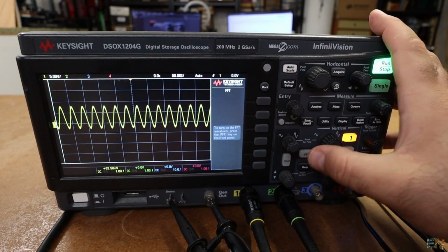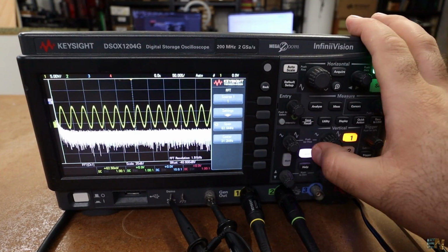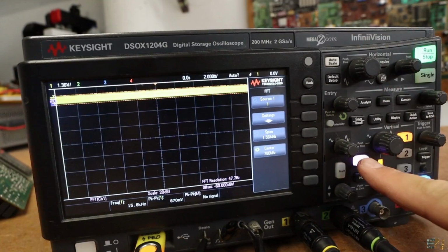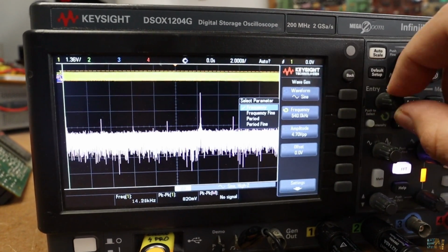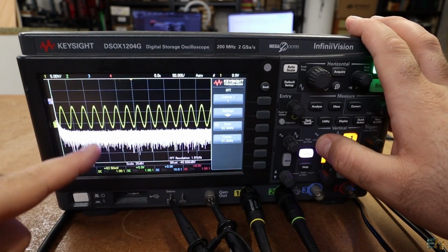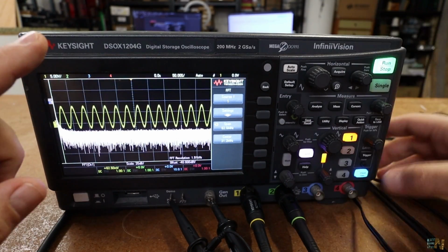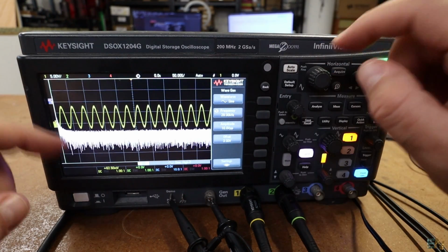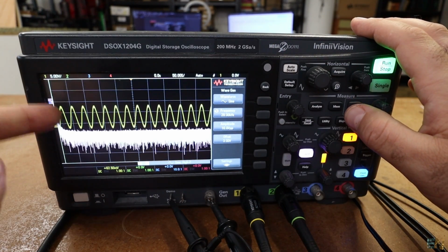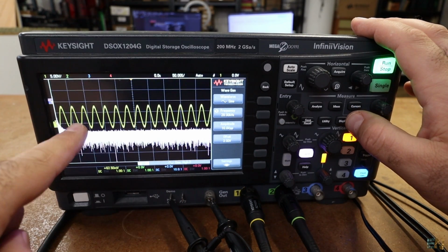Okay, so the last button for measurement that I want to show is the FFT, or fast Fourier transform, and when you activate it, as you can see, you get all the spectrum of frequencies. Let's just imagine like radio frequencies. It could be more than radio, but let's just imagine that. So this is just the spectrum in megahertz or kilohertz, and now we have connected our signal, which by the way comes from the generator, and it is at 29 kilohertz. So basically we have a line just down here at 29 kilohertz, because that's a very low frequency value.